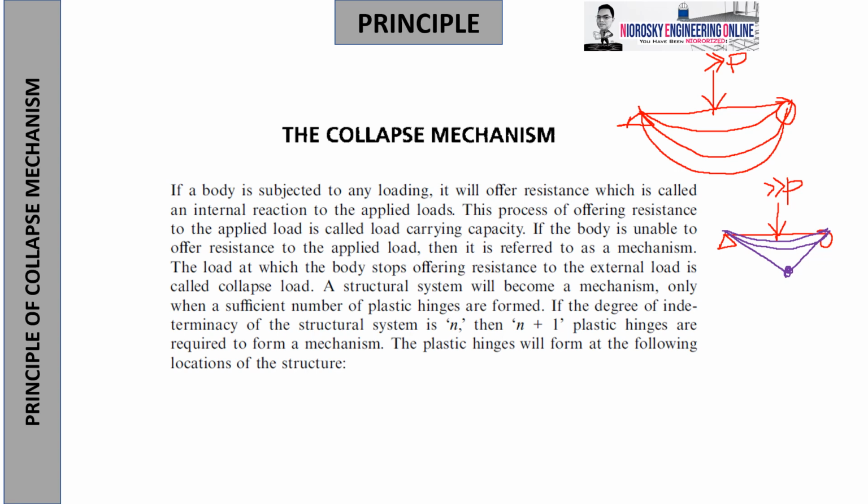Unlike concrete, where when it cracks there's what you call the acceptable crack width, that is hairline width. But here, there's no such thing as hairline width; as long as the steel performs, then it should be designed. That is the definition of the collapse mechanism in the shortest possible way that I can explain. And the N and the N plus 1 represent the hinging effect. I'll discuss later how the hinging effect takes place in a structural steel member.